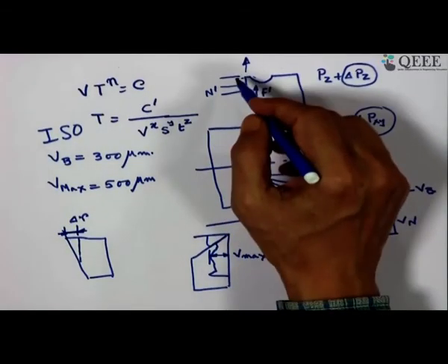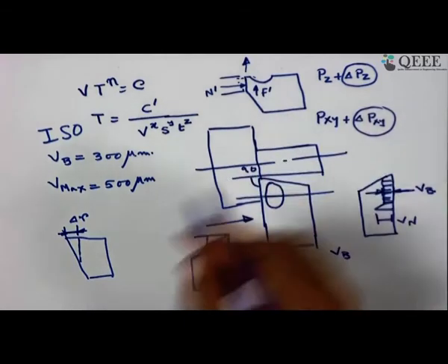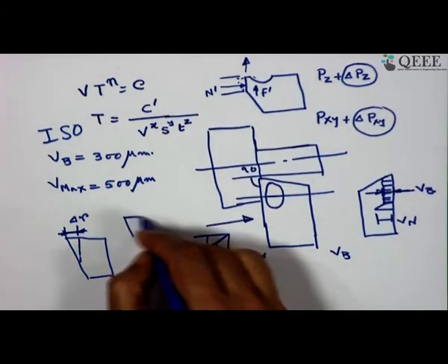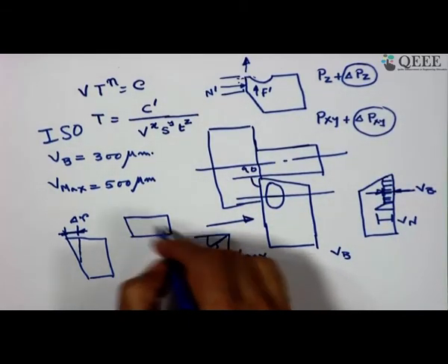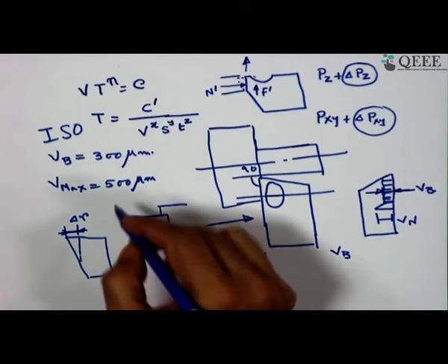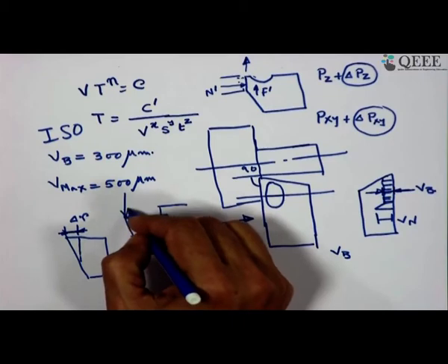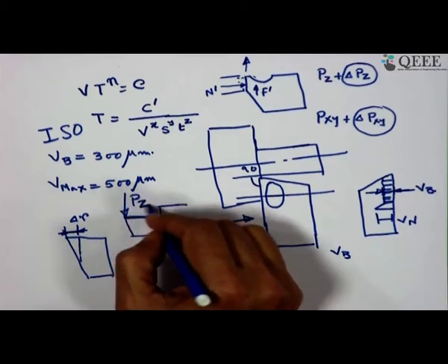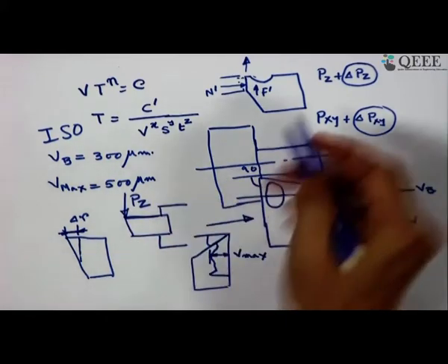And what is the other limit? Other limit is that power keeps on increasing, that is one thing. And then because of the addition of this Pz, one thing we should also take note of, that if this is the cutting tool which is supported, it is a cantilever like thing, and here this is the reaction force Pz.